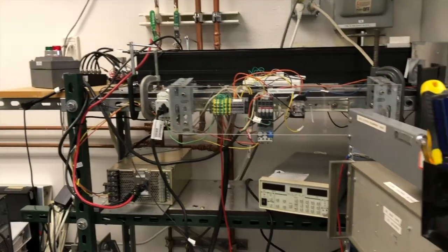It significantly reduces the temperature required to sinter ceramics, and it also significantly increases the rate at which that sintering happens. So rather than the typical sintering times that we are used to with ceramics of many, many hours at very, very high temperatures, for example, for aluminum oxide, that temperature can be 1,500 or 1,600 degrees. With the presence of the electric field, we can bring that sintering temperature down, the sintering times down, so that you can actually get sintering while the laser is scanning.